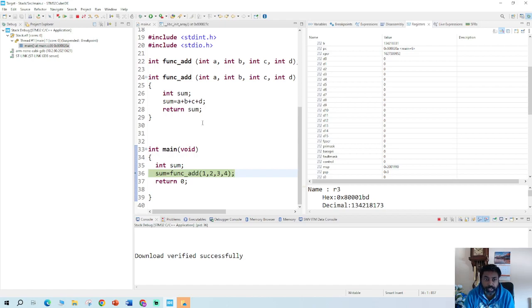You don't have to go deep into the assembly language. This is just for our understanding, to learn how the stack works. You can see for yourself how the stack pointer can be changed from MSP to the PSP location. So bear with me one moment while I write a small snippet of code.